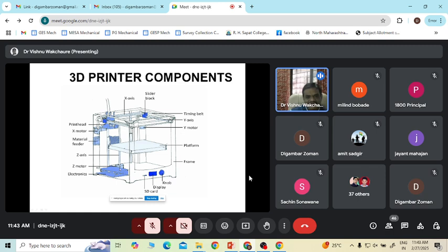We will have a Z motor, and there will be electronics to control this particular X, Y, Z. So basically there will be three axes, three motors, three lead screws, and a machine control unit which will control the simultaneous movement of the nozzle, right? Here you can see the timing belts and all these things. If you have seen a CNC machine, or simple 3D printers, the basic thought is the same. You have to control the tool, meaning the nozzle, and the movements in three directions, X, Y, Z, and accordingly you need control electronics for controlling the movement, right?